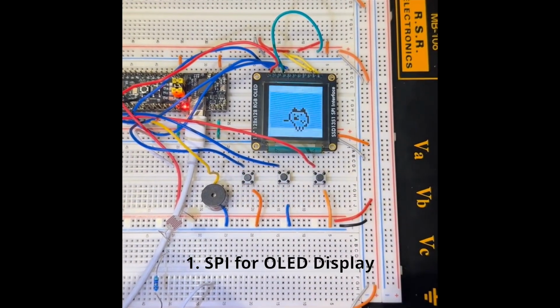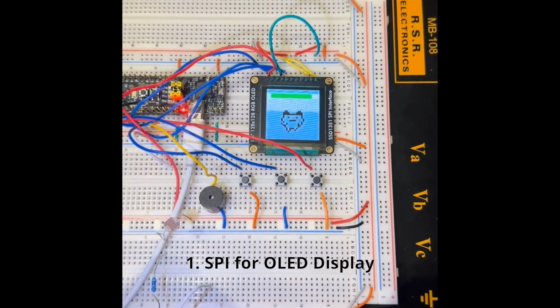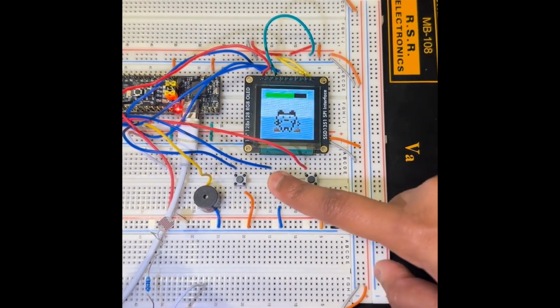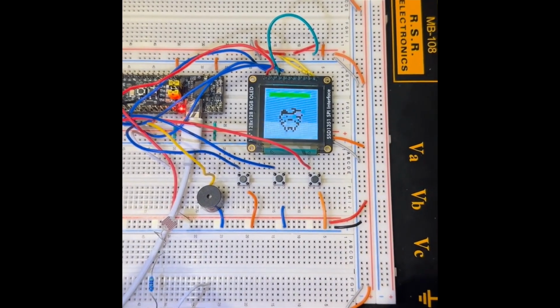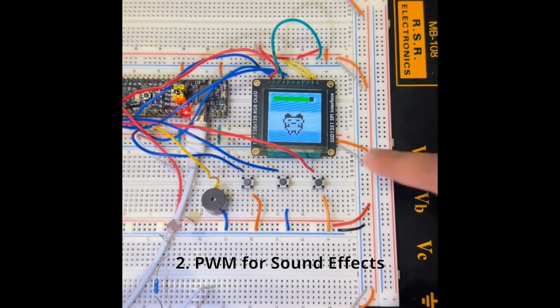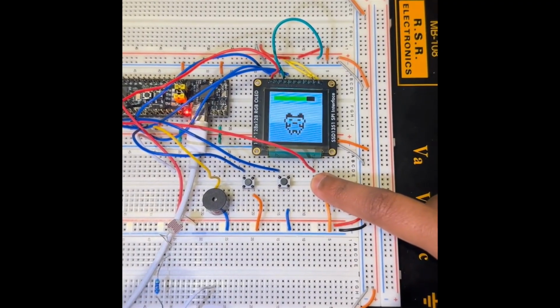First, we used the SPI peripheral for the OLED display to smoothly and quickly cycle through different bitmaps based on the state of the TomaByte pet, as well as decreasing the health bar and changing its color depending on the pet's condition. The second peripheral we implemented was PWM for the sound effects of the pet through the buzzer.